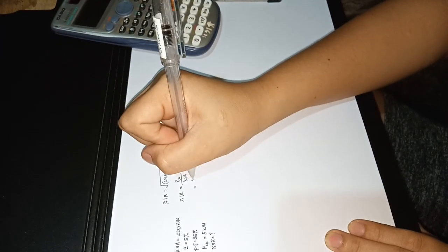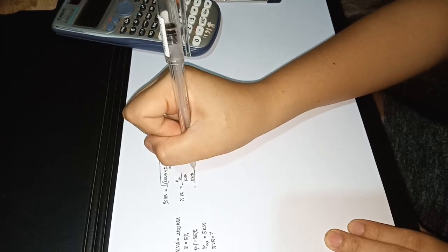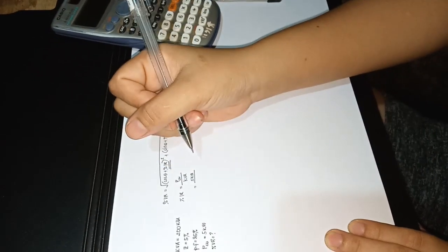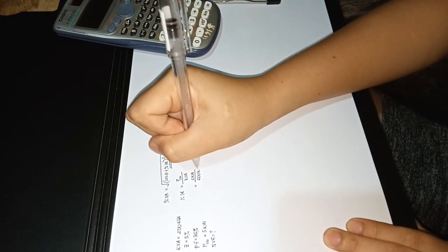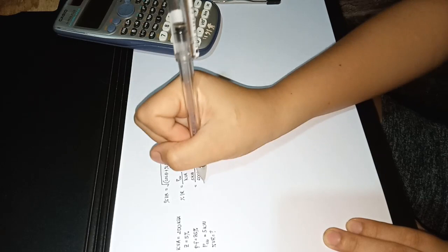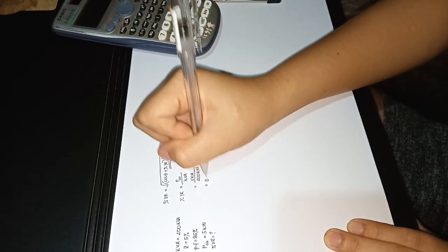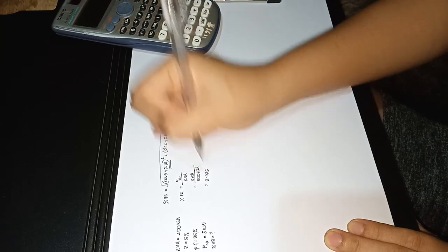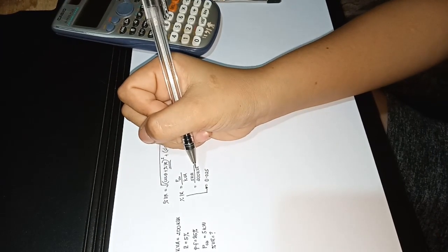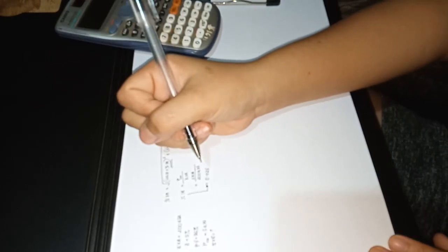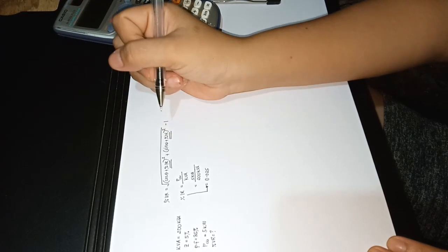Copper loss is 5 kilowatt over the 200 kVA equals 0.025. So percent IR is 0.025. Next, we have to find the value of percent IX.